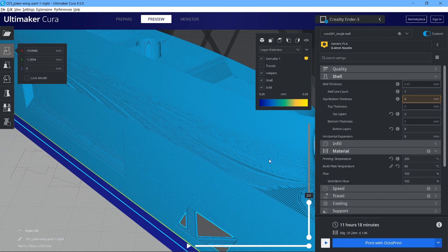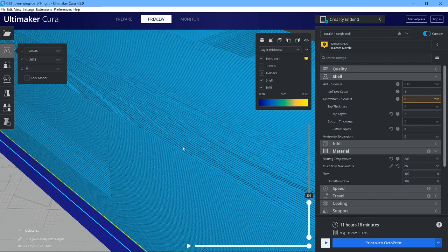And that's what I found in my first print. There were lots of holes, and it really wasn't a fully structured center section to the wing anymore. And if you zoom right in, you can see where it's actually filled in various lines and the way it's bridged these together. In fact, if I didn't use this technique, you'd see a line here and a big gap. So what it's doing is filling in these lines in an adaptive way to make sure that this compound curve is fully filled in.